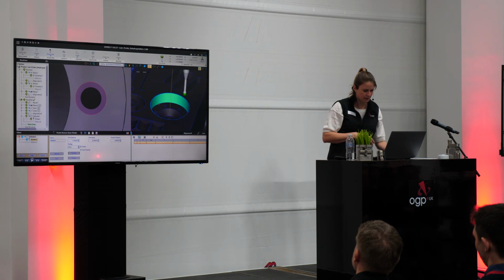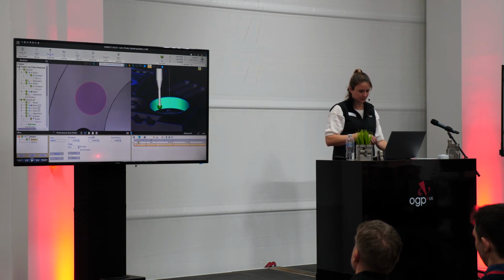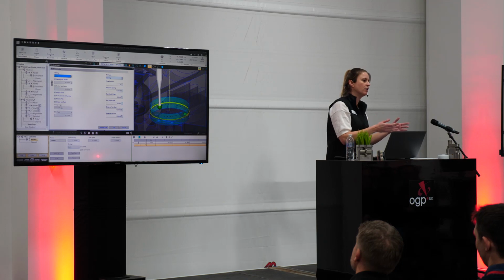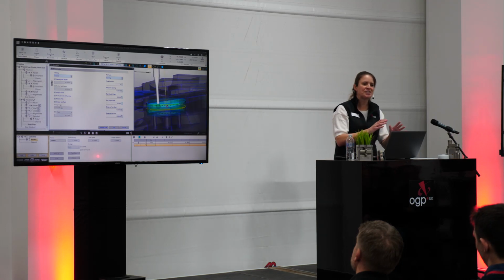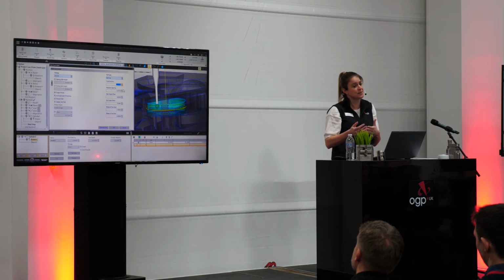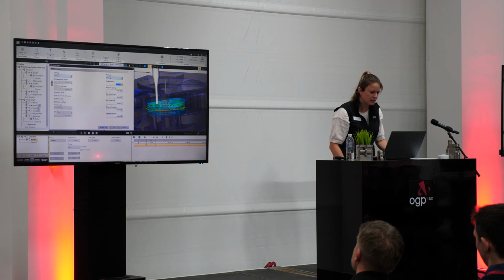So I think I do that now. Yep. So if you're using a different tool, meaning video versus probe, there's different settings in this path generation window, because obviously the sensors have different capabilities. But again, the workflow is the same. So here I'm changing how many sections I want to scan on the cylinder.